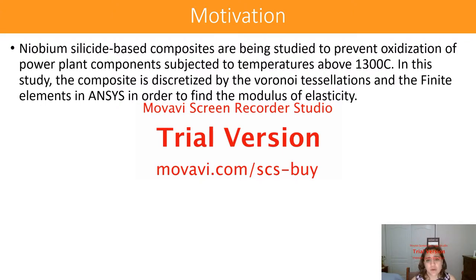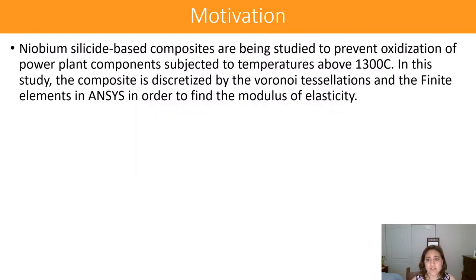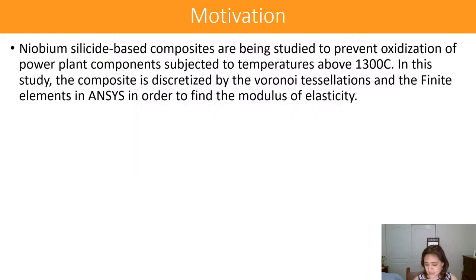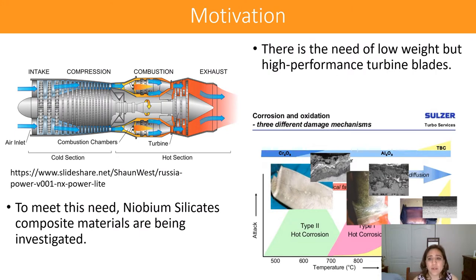Niobium silicide composites are being studied to prevent oxidation of power plant components subjected to temperatures above 1,300 degrees C. In this study, we discretize the sample using tessellations and the finite element models in ANSYS to find the modulus of elasticity. As you may know,